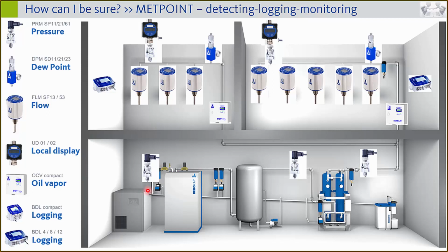It's regularly recommended to see what's the outlet pressure of the compressor, with a second pressure sensor after the vessel, and a third one after the desiccant dryer. In combination with the data logger and so-called virtual channel settings, we can easily identify the pressure drop around the desiccant dryer and around the BEKO cut, which is an indicator for preventive maintenance, for example, or to realize that some particles are collected at a higher level and so on. So that's the reason why we put in these pressure sensors.